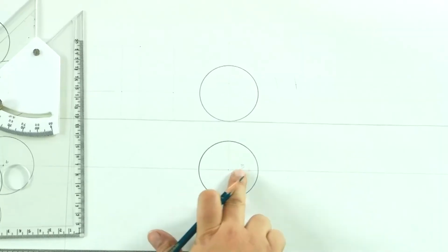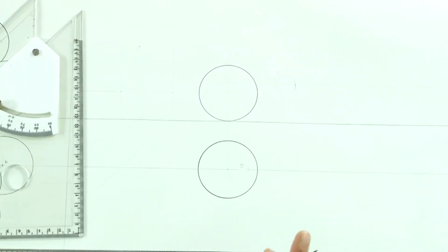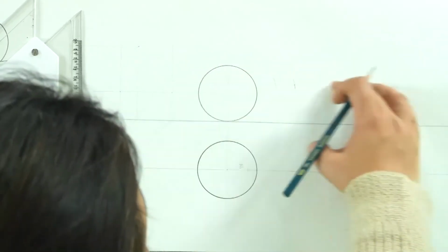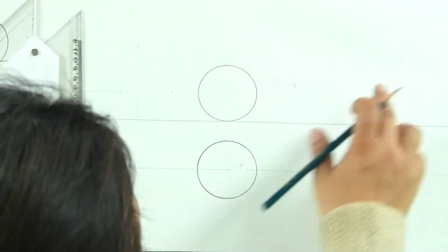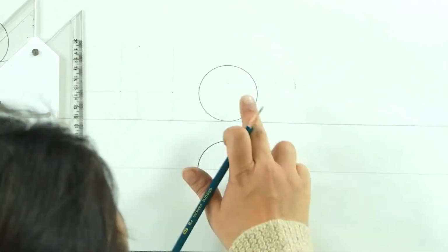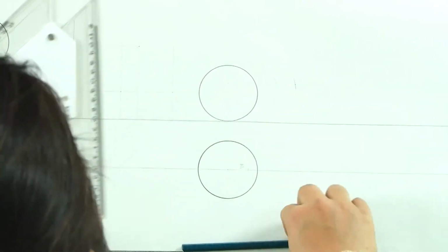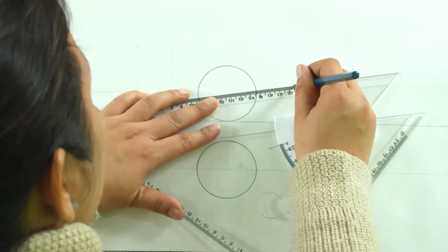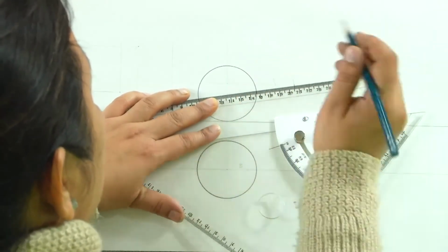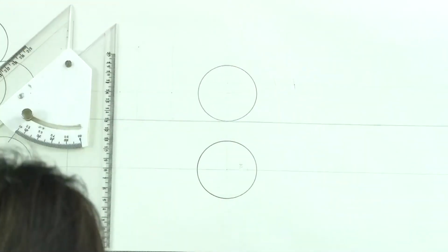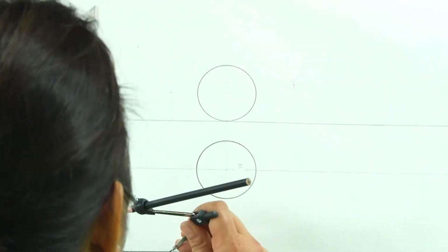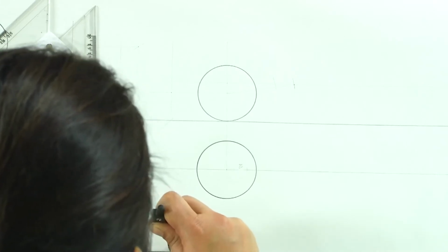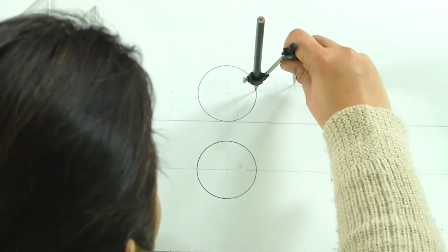And this line we assumed, the given condition is that the line joining the two centers is parallel to the VP. So this is going to remain straight, while the line joining the two centers will not be straight anymore. So this line is making a certain angle with the HP, and now we will take the 4 centimeter in the compass with this as the center.